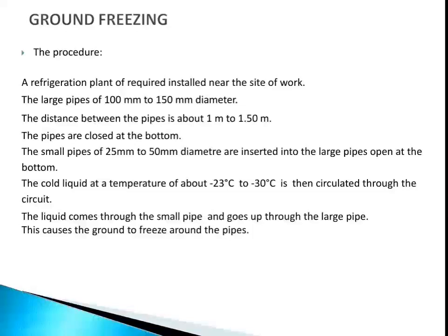Large pipes of 100 mm to 150 mm diameter are used. The distance between these pipes is about 1 meter to 1.50 meter. The pipes are closed at the bottom. Small pipes of 25 mm to 50 mm diameter are inserted into the large pipes, open at the bottom.